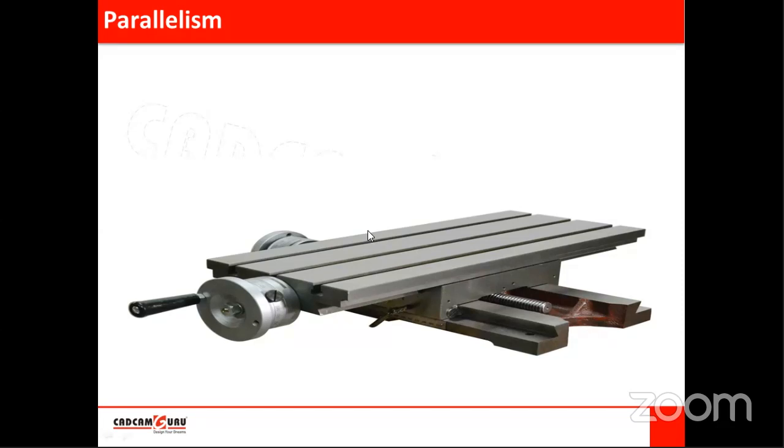So again, you can see here a machine-made component. Here you can find different T-slots to hold the fixture assemblies on this component, or there are slideways, or you can say guideways. This complete table is moving. In this direction it can move, or in this direction this table can move. So for smooth motion of this component, these guideway surfaces should be parallel to each other. So these guideways should be parallel to each other.